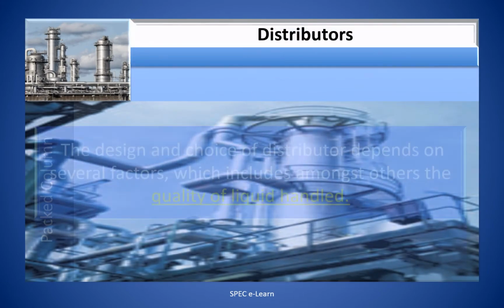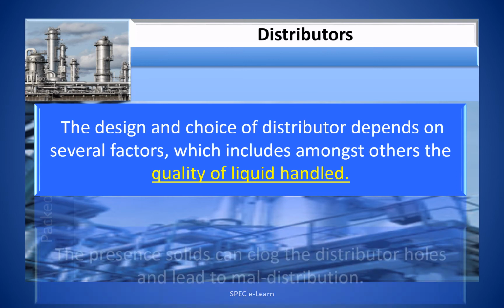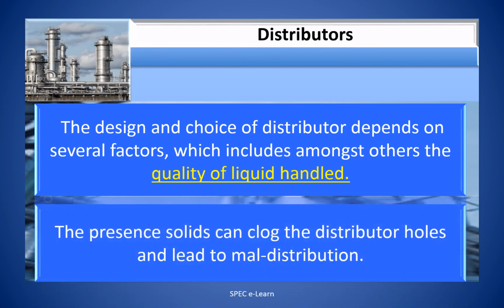The design and choice of distributor depends on several factors, which include, amongst others, the quality of liquid handled. Presence of solids can clog the distributor holes and lead to maldistribution.